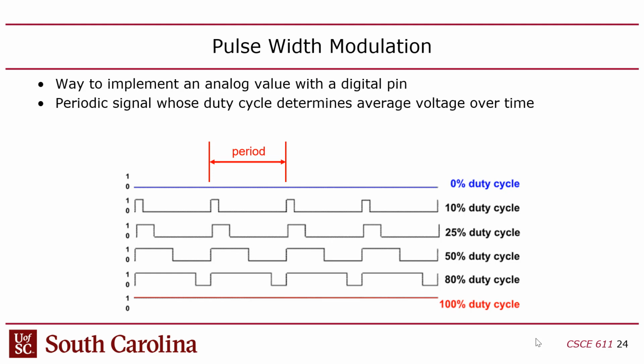Is there any advantage of going faster? Yes? We experimented with making the frequency greater, like making the period smaller, and found that the motor didn't really work with that. Anything much faster than 10 kilohertz, it didn't seem like it could respond. That's interesting. I hadn't tried anything faster. Kind of surprised that it doesn't work. It could have to do with the H bridge and how fast it can switch internally.